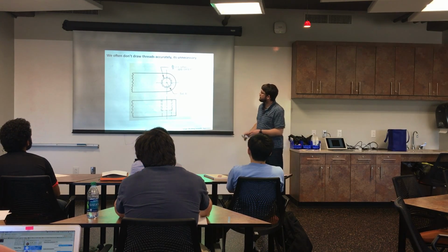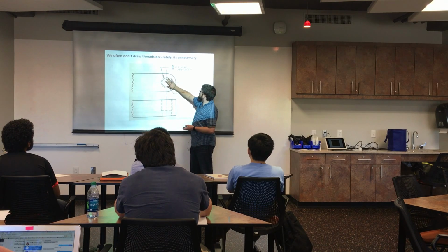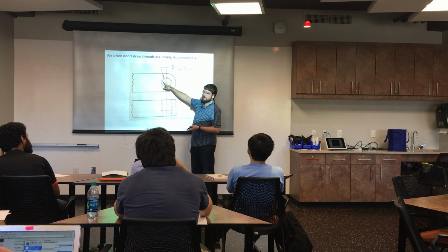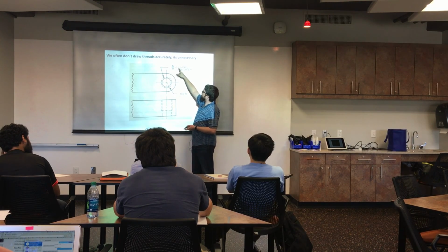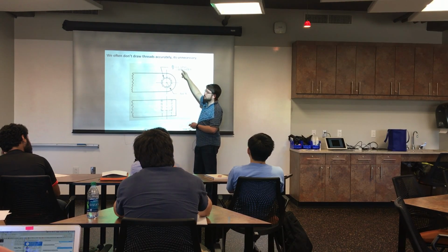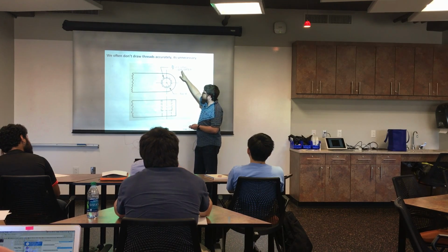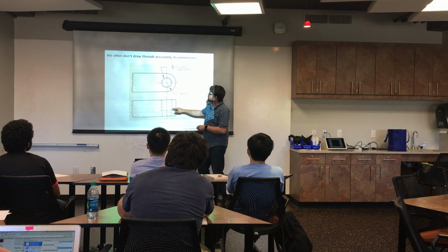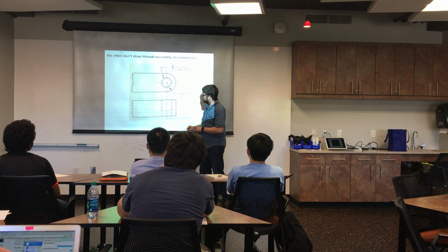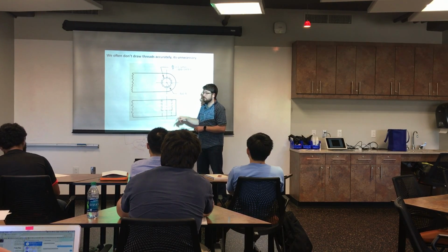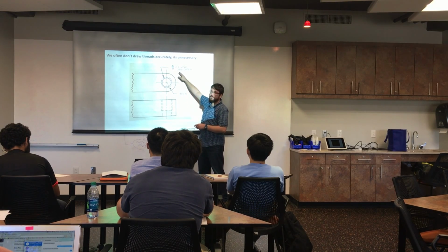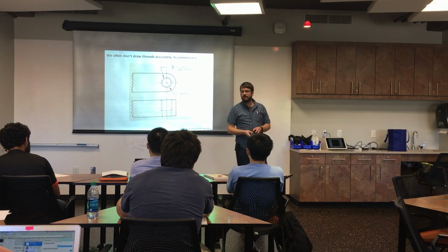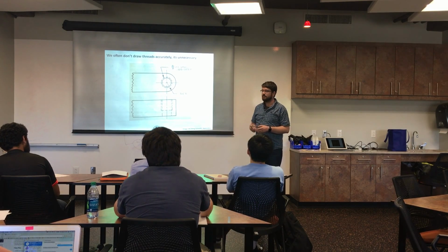Another example, this is a bracket that's got a hole through it, and then we've threaded that hole. So this would be the drill diameter, that inner part, and then specifying 5/8-11 UNC, Unified National Coarse, remember we talked about in threads, 650 thou deep. And this is what it looks like in cross-section. Or, sorry, this is what it looks like from the side, and then they drew hidden lines. They didn't actually do a section here. And you see that the threads do not go all the way through the part. That's why they specified 650 thou deep here, because they're only going partial depth. That is not uncommon in some parts to have that.